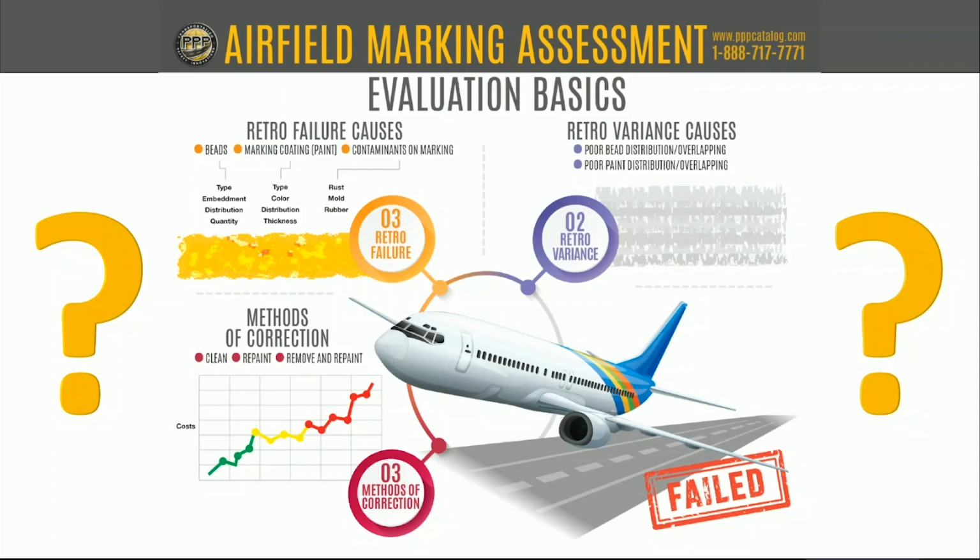I'll kick that one off too. In the roadway industry, thermoplastic, because it's so thick, is usually 90 mils plus, so 90 to 125 mils. It's so thick compared to, remember what I was just saying, 15 wet mils, which dries down to about 10 dry mils or so. So you have 10 mils of paint in comparison to 90 mils of thermoplastic. So it will last nearly that many times longer.